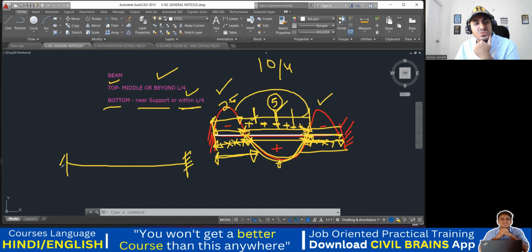any beam in the sense a fixed beam, and if I try to plot the negative and positive bending moment, it has been found the effect of negative bending moment is predominant, or more effective, up to L by 4. This is L by 4. Beyond L by 4, your negative bending moment is very less and it will turn into a sagging bending moment.